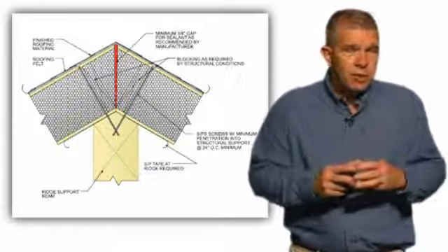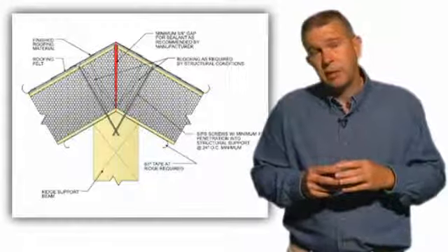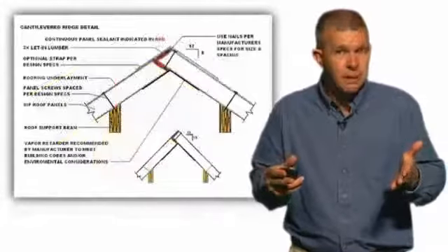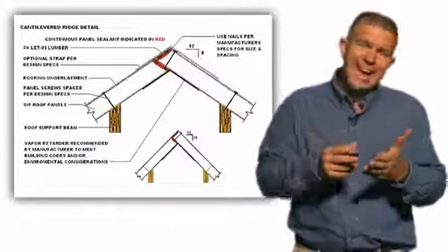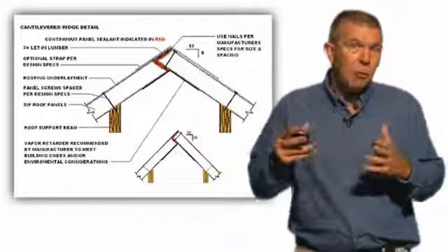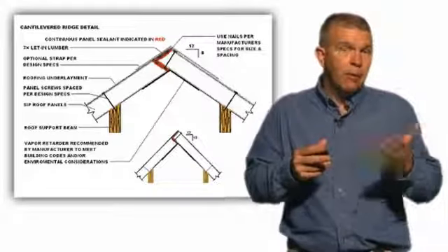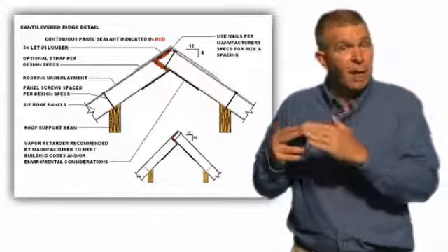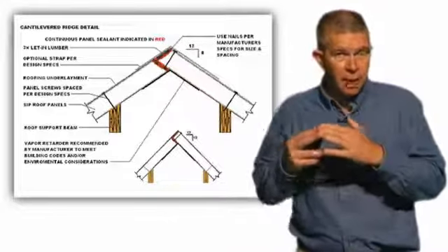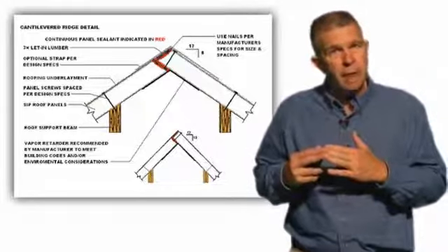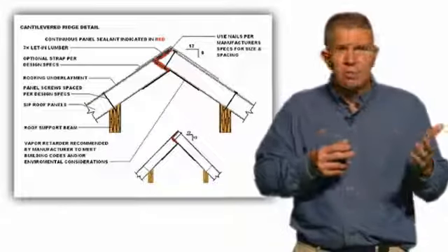If we don't want to go with a single ridge beam, we actually have the option of getting rid of the ridge beam altogether and going with offset ridges or purlin beams. And now we've, in essence, shortened the span of that roof panel. We've put the panel into a multi-span condition, and we've allowed the end of the panel, which is the ridge, to be tied to the opposite plane or the opposite roof plane, and then incorporate some of the loading over into that. This offset ridge